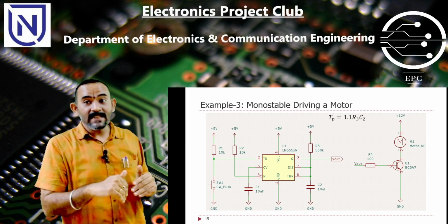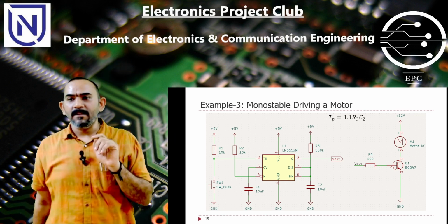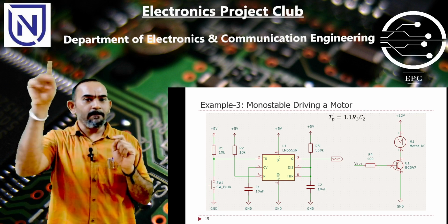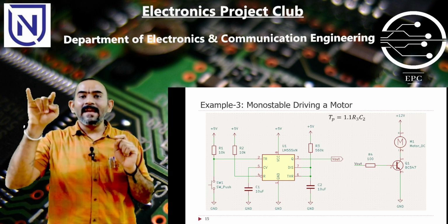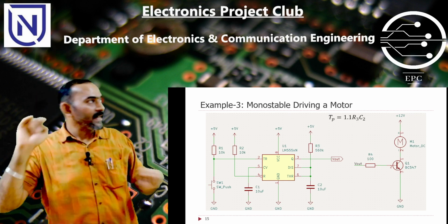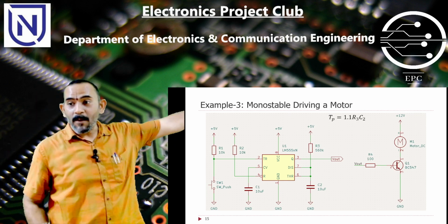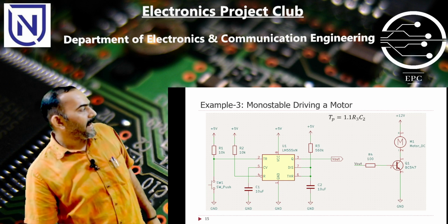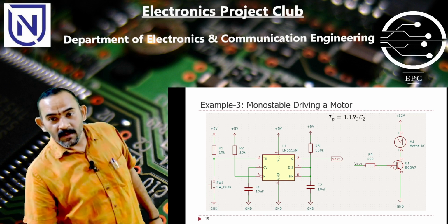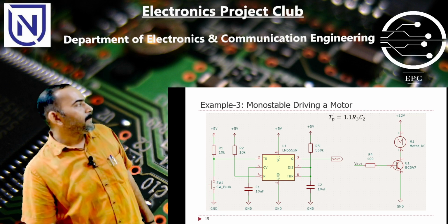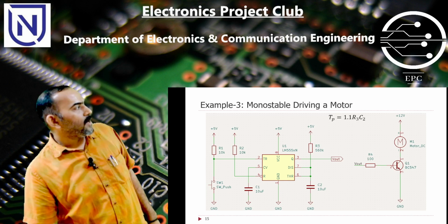So what design I have done, I have taken a monostable multivibrator, which we know, once we trigger, will generate a pulse, and I can fix the pulse width. I know that it should run for 5 seconds, so I use an appropriate resistor and capacitor. The values are here, 560K and 10 microfarad. This gives me around 5.6 seconds of pulse width, obtained using this particular formula.